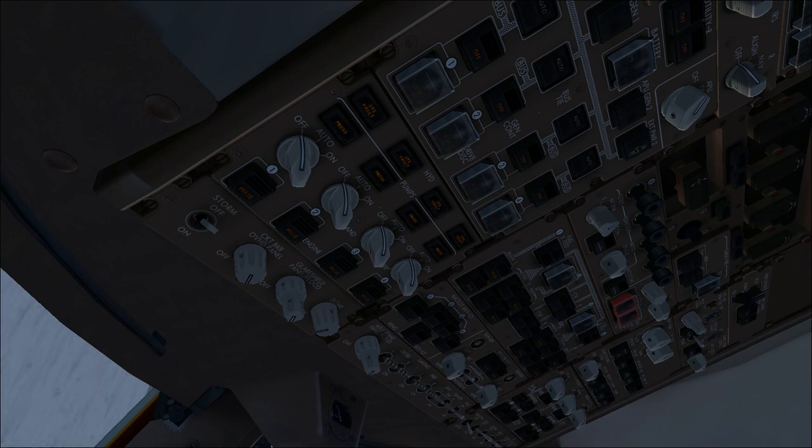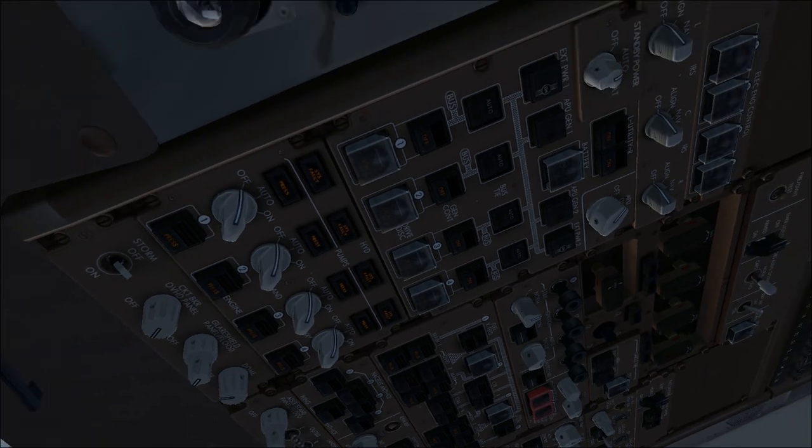This can be done pretty easily by turning the standby power knob to BAT, that is the last position on the right. This procedure is useful because you check that in case of some problems on the AC power, you will have DC power converted to AC power by the inverter.